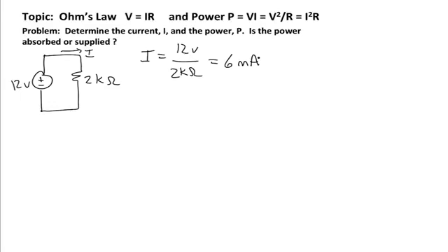We determine the voltage across the resistor using Ohm's law, but we also are using loop analysis, but we also have to use the passive sign convention. Passive sign convention tells us that the current is assumed to enter the positive side of the voltage polarity on an element. The passive sign convention is absolutely critical to determine power flow in a circuit.